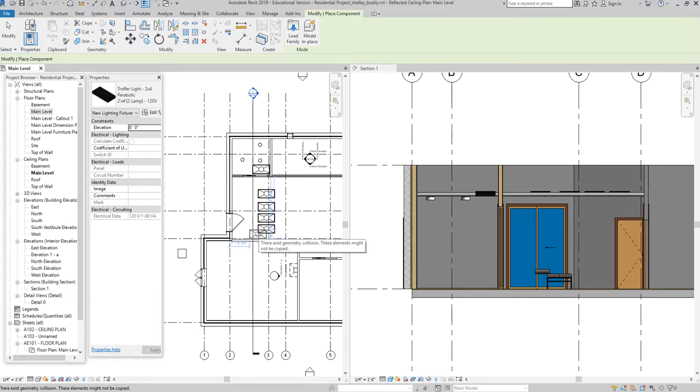Okay? So my explanation, I'm just going to explain this, right? And we've talked about why this is happening, so I think you know that, but there's always a debate. Do I take my floor, right? Let's talk about a residence. Do I take my floor, and when I build my floor assembly, if there's a main level and a basement, I create my main level structure, I put the finished floor on top of it, right? And then to create my ceiling, which is the bottom side of my floor, do I just add gypsum board to that assembly? And then gypsum board shows up in my basement as my ceiling. Great, right? That's pretty easy. And it's a valid way of thinking about it, right?